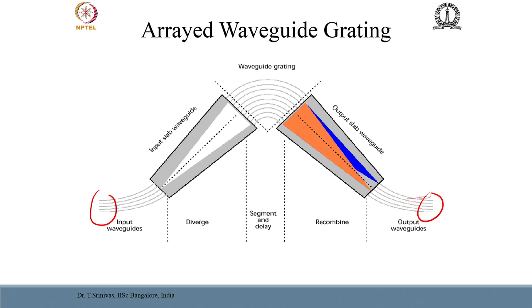So, the operation is like this. First of all, the light is mixed up in the region and redistributed across all the inputs of the waveguides, and the waveguide lengths are unequal, creating different phase shift across the output of the waveguides. So, the light coming across the first port has the least delay, and the one which is coming out of the outer port has the maximum delay, and the lengths could be designed such that the phase shifts across each of these when combined at the output port could lead to superposition only at one port for a given wavelength.